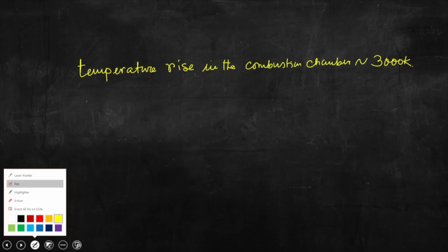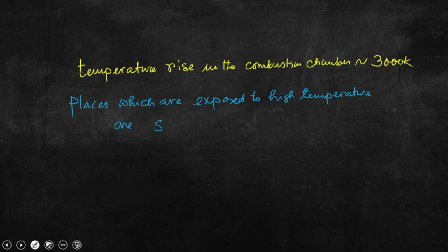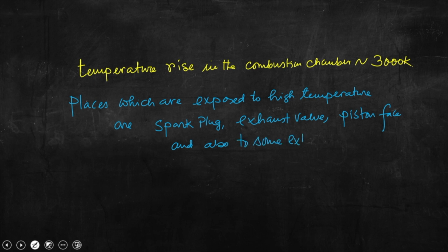So, let me write here, which is very important to know at this time, that places which are exposed to high temperature are spark plug, exhaust valve, which is very important to know, intake piston face and also to some extent intake manifold.